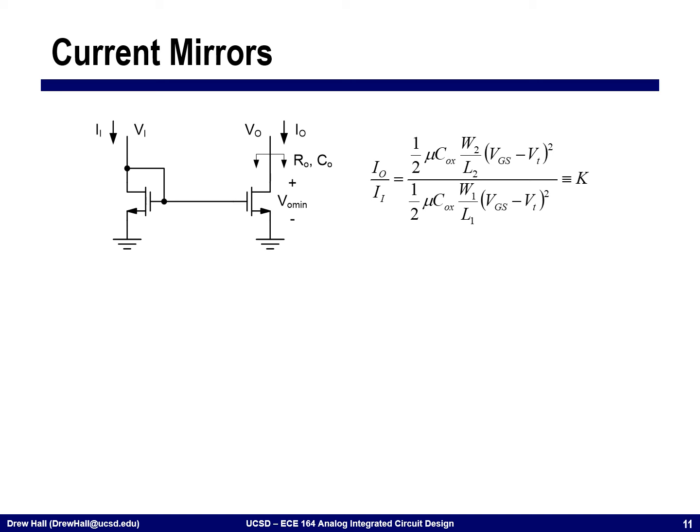We talked quite a bit about current mirrors for biasing, the idea going back to the process, voltage, and temperature robustness of these circuits, that we would rather use other transistors that are physically located very close to the transistor that we're trying to bias, in this case, these two transistors here. What this allows us to do is the diode connected device, quote unquote, computes the right voltage that we place at the gate here in order to have these two currents match. So I out is equal to I N.